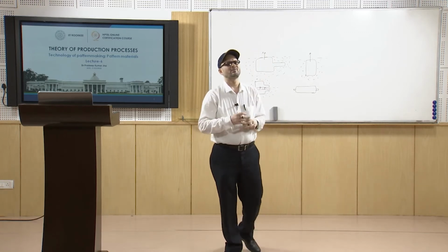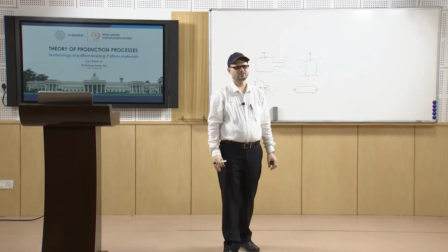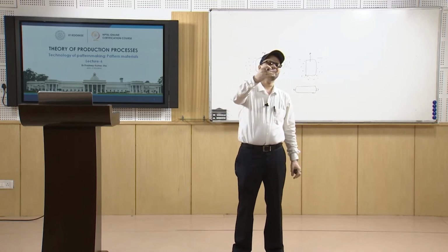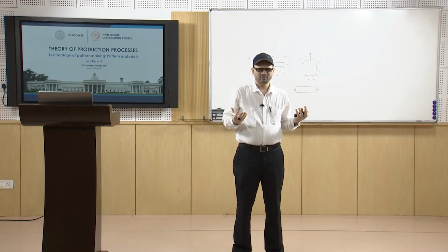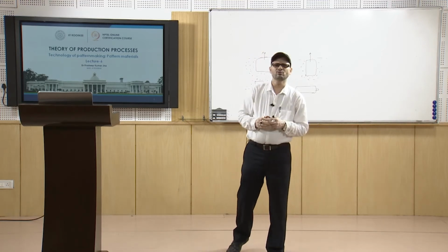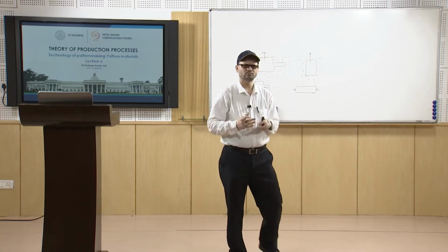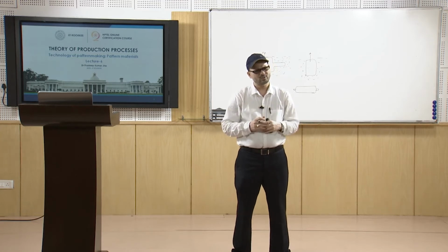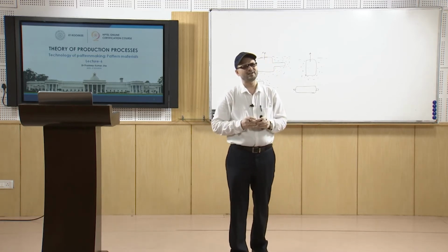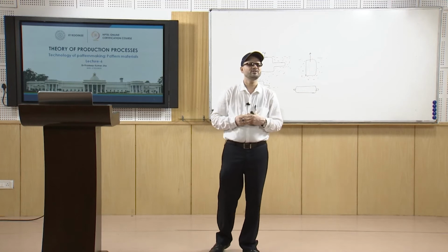So, that way wood serves the purpose. Apart from that, you have other materials also like metals. We will discuss different kinds of materials. The next condition is lightweight. Lightweight is important because if it is heavy, in case of manual movement, it brings fatigue to the worker who is carrying it, or you will have to have extra means to transport it if it is quite heavy. So, it should be light. If it is lightweight, then it is better. That is one of the desired characteristics of pattern material.